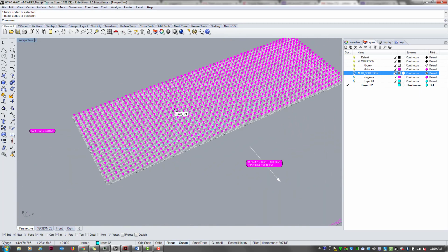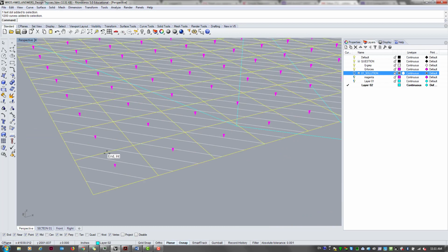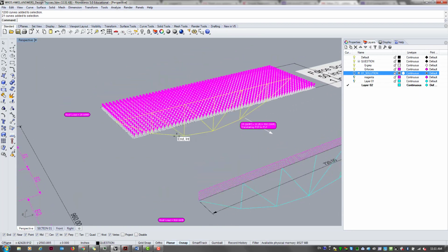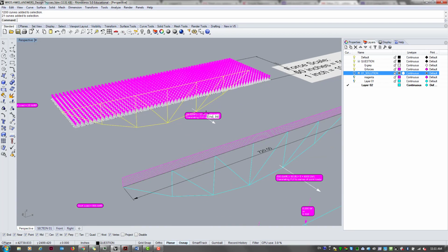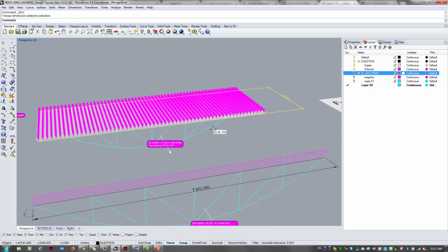I mean, it wasn't necessary, but I'm just showing you, this is a roof load of 25 pounds per square foot. Each square is a square foot, and each of these is 25 pound force. So because this one truss is taking care of that area, what you do is basically squish that whole surface into a line, right? So that's 25 pounds per square foot, but this 20 feet width is being taken care of by this truss.